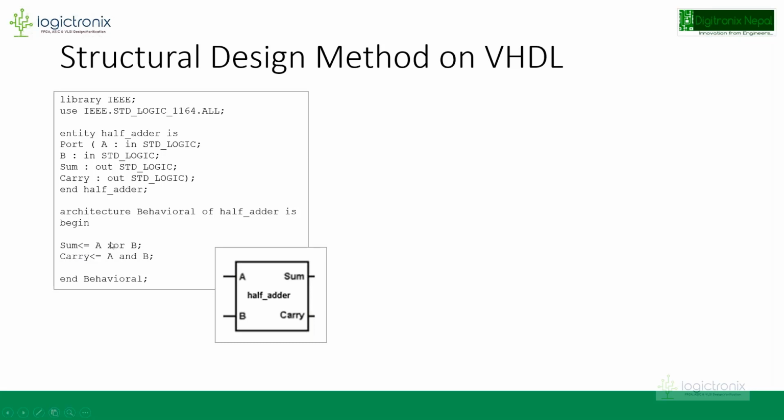So it actually did the assignment. What that means is the result of A XOR B will be sent to the sum. So this operator did the assignment of the right-hand side result to the left-hand side operand, or the port or the signal. Basically, we have another port, the output carry, which is A and B.